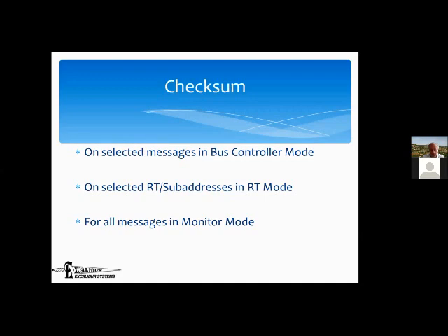Now, on our cards, at least, in monitor mode, we always figure out the checksum, and we set a bit in the status telling you whether there is a valid checksum in the last data word or not. Now, as opposed to most other bits in status words, this is not an error condition. It's up to the user to decide whether it's an error or not, because if there was no checksum expected, then the fact that the checksum didn't match is not an error. If there was one expected and it doesn't match, that is an error, and it's the application who's likely to know whether he was expecting a checksum or not.